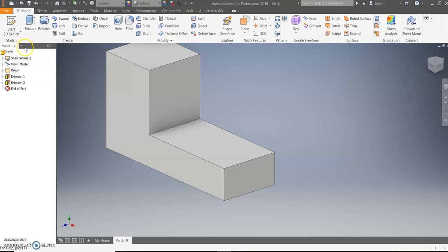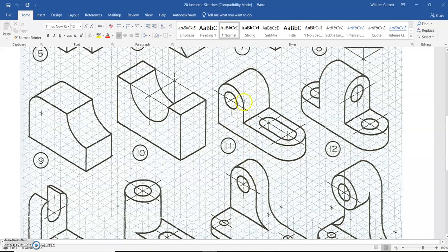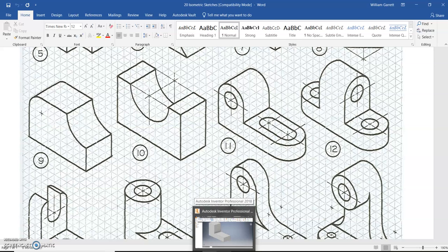There's a variety of ways to go about doing that. So to start, I'm going to fillet these edges. If we look at these edges on both sides of the shape, you can see it fillets. And if we count 1, 2 is our radius, same thing down here. We have a radius of 1 and 2. So we can do both of those at the same time if we want.